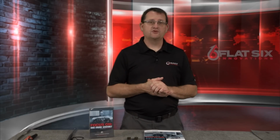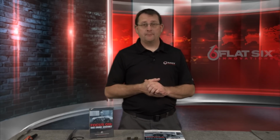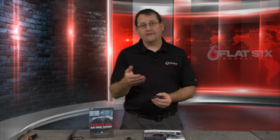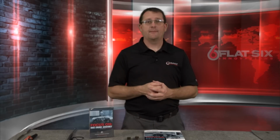So I hope this instructional video has helped you understand what camshaft deviation is and some of the factors that play into it, as well as how to address it. Most people who watch this are, of course, going to have that 5-chain engine with those infamous chain wear pads that are going to end up wearing and create those big camshaft deviations that are going to require some intervention. So if you're one of those people, I don't want you to be afraid to tackle the job yourself.